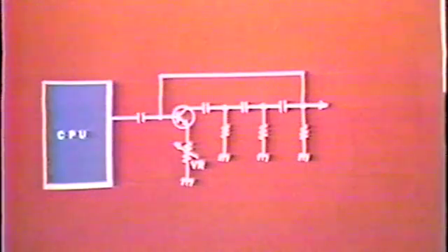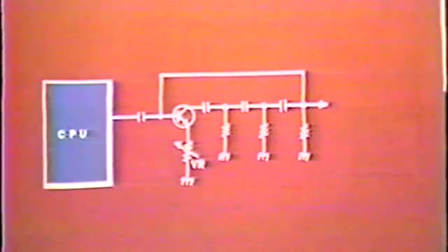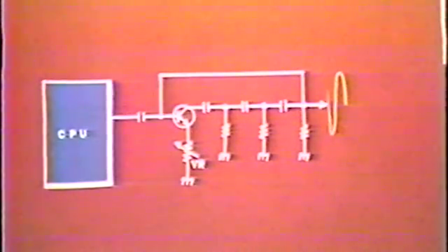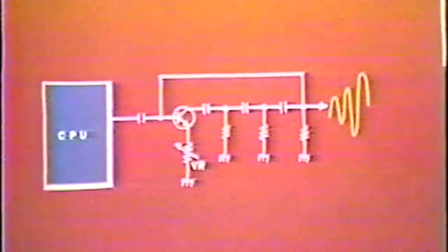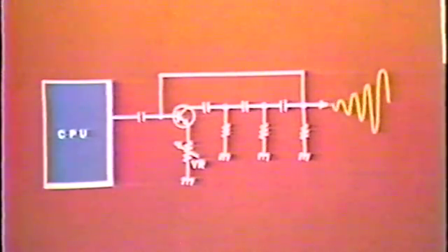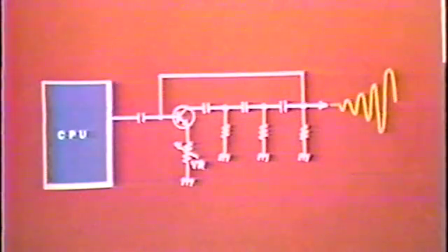Oscillating sounds are created by an oscillation circuit. The trigger pulse output by the CPU is emitted from the collector of the transistor, is time delayed by resistors and capacitors, and is fed back to the transistor base, causing it to oscillate. The oscillation frequency is determined by the resistance and capacitance. The feedback current drains to the ground little by little through the transistor emitter and variable resistor. Therefore, the oscillation waveform gradually becomes smaller. The attenuation time of sounds is determined by adjusting the variable resistor.